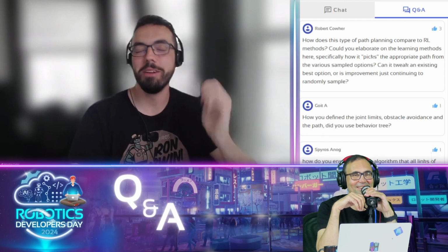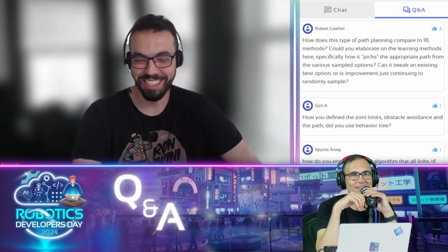Oh, well, that question is basically a whole history of motion planning, right? Because the first ever implementations of sampling motion planners were the very stupid thing as you described, right? Which is just keep randomly sampling, maybe something better will come along. Then there have been variations on these planners that actually try to use some real information to shortcut paths. The thing about these methods is that it's hard to get them to do something very optimal, but because you're actually implementing these algorithms and checking collisions, you can guarantee that the paths will at least meet the requirements that you're validating against.